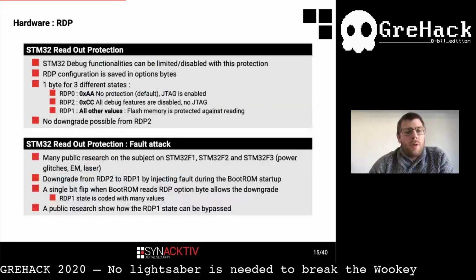The next big part is the fault injection tests. We see that the Wookey uses STM32 protection to disable JTAG. This protection is called RDP. The STM32 has option bytes stored in memory, and the RDP is one of these bytes. The RDP protection can have 3 different states.